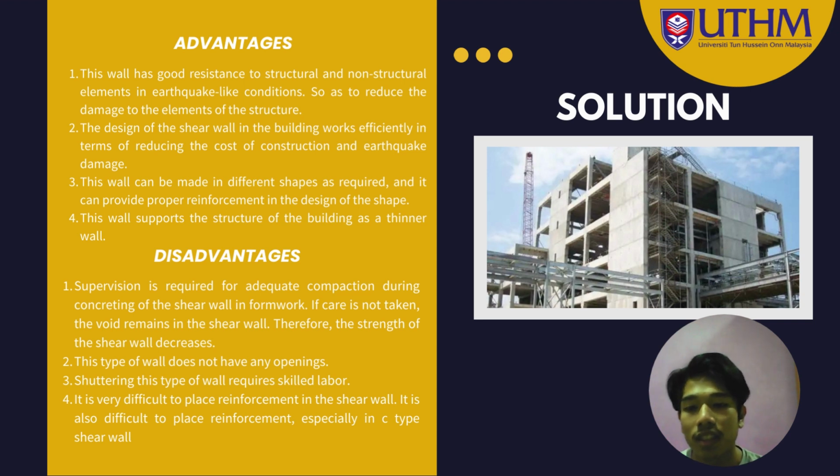A disadvantage of shear walls is that supervision is required for adequate compaction during concreting of the shear wall in formwork. If care is not taken, voids remain in the shear wall. Therefore, the strength of the shear wall decreases.